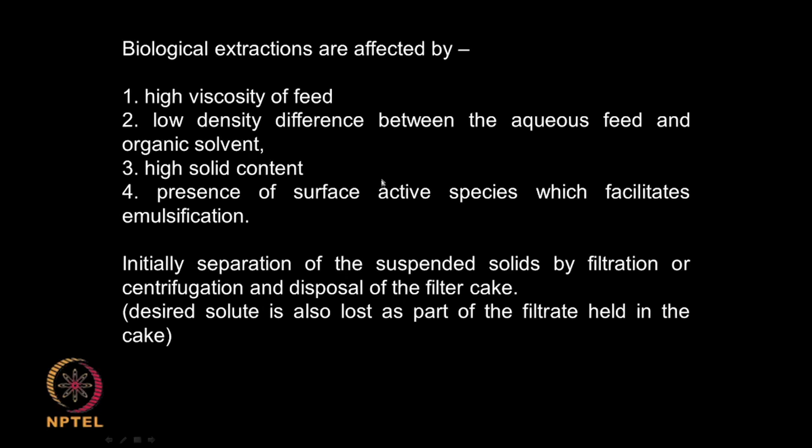Because of all these reasons you may have problems in extraction, but extraction is one of the best methods in biological systems. Like I said, your proteins, carbohydrates or even enzymes may be very thermally labile, and you might not be able to use techniques like distillation or other high temperature operations, whereas in liquid extraction you can work at room temperature and even with buffers.